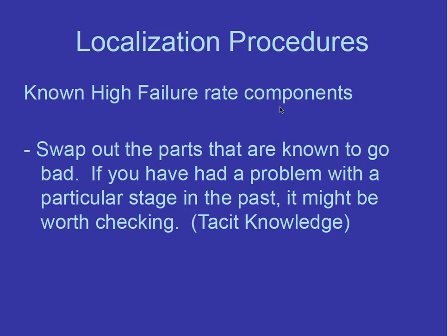So you should know which components are sensitive and have a higher risk of failure. So swap out the components that are known to go bad, even if you don't know whether that component is bad or not. You can replace it with a new one, and then see the performance.